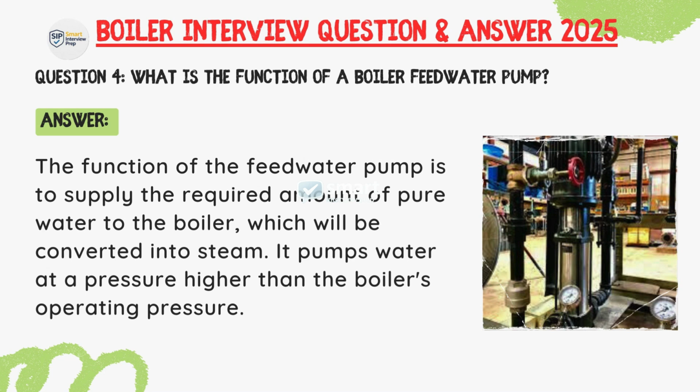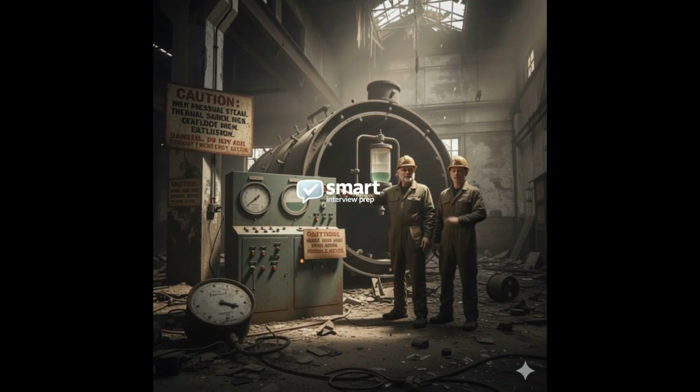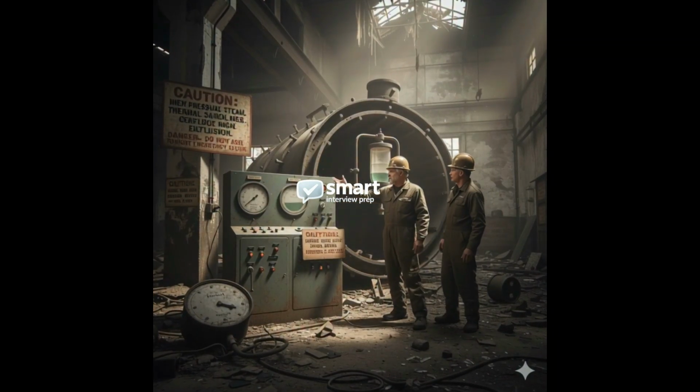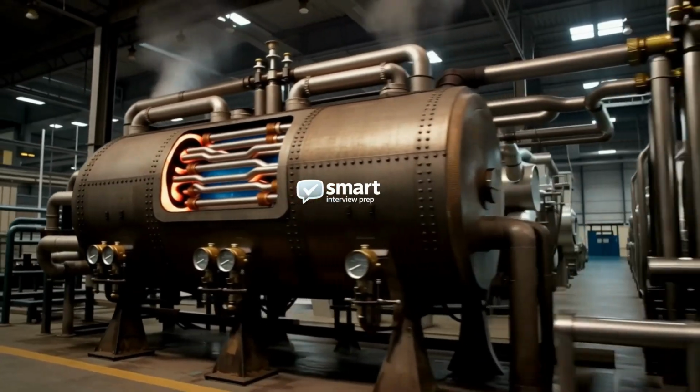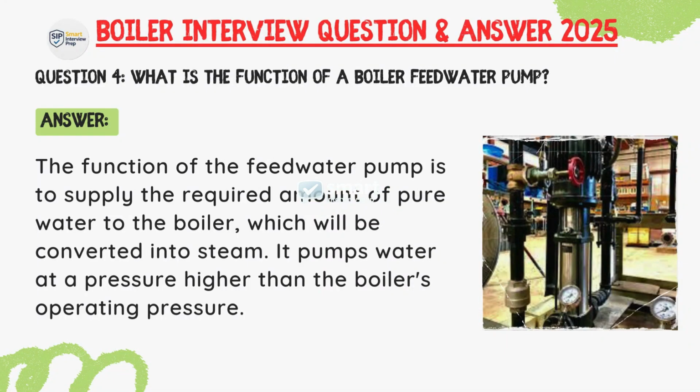Question: What is the function of a boiler feed water pump? Answer: The function of the feed water pump is to supply the required amount of pure water to the boiler, which will be converted into steam. It pumps water at a pressure higher than the boiler operating pressure.